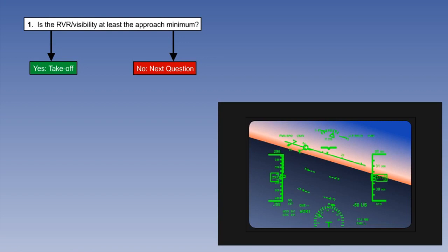Obviously, the aircraft should land and resolve the engine problem as soon as possible. Preferably, the flight crew would like to land back at the departure aerodrome. Therefore, the departure minima would have to include the approach minima and may have to increase to do so. For example, if a Category 1 ILS is the best approach option, it requires an RVR of at least 550 metres. The takeoff minima must, therefore, also be 550 metres.